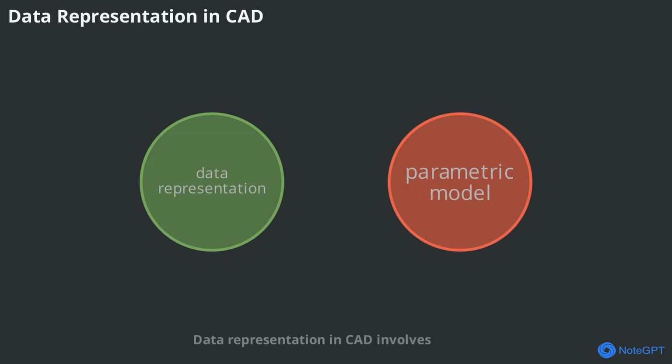Data representation in CAD involves storing geometric and non-geometric information mathematically. Wireframe models use vertices and edges, surface models employ NURBS for complex curves, and solid models define complete geometry with topology. Parametric data stores features as parameters and constraints. Accurate data representation eliminates errors, enables scalability, and simplifies modification. Feature-based models update automatically, ensuring consistency across drawings and assemblies.